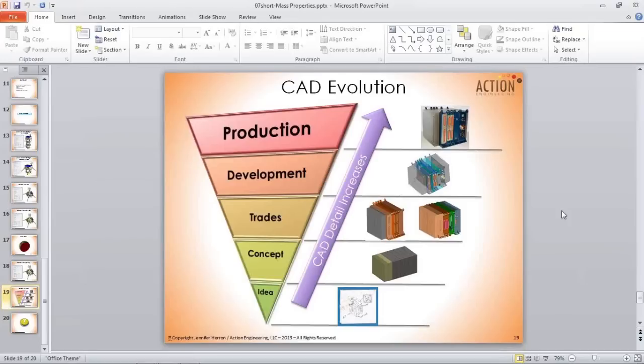Kind of a thought that I had related to model-based enterprise is that if you actually have 3D GD&T inside the model, you may have tolerances, and you could actually possibly do a study using tolerances at various upper and lower levels to determine minimum and maximum mass. Would you normally do that with the CAD system, or would you use special tolerance analysis software for that?